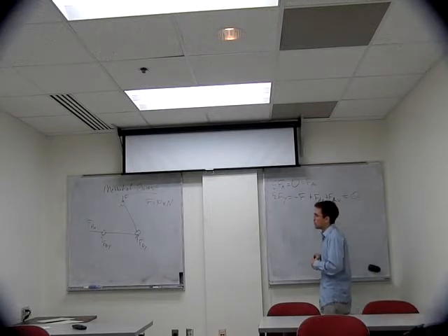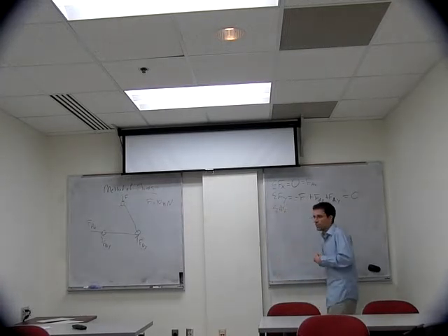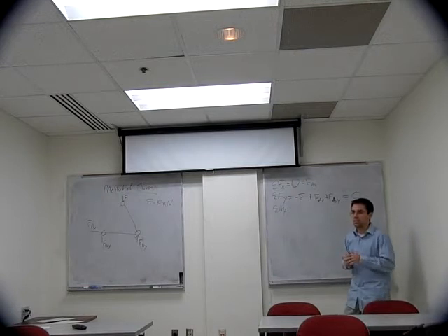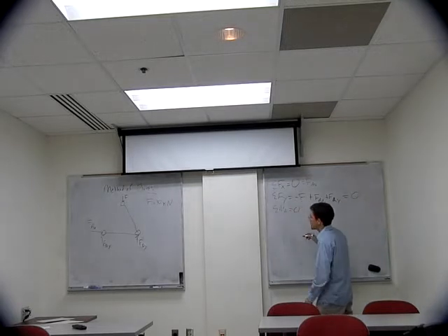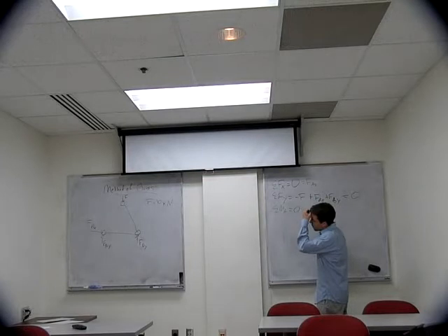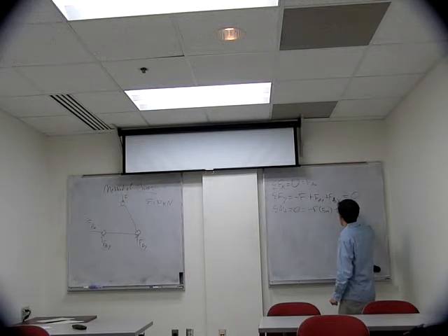So what we can do is take a moment around joint A. We know that since this is just a pin joint, there can be no torques around this joint. So this moment has to be equal to 0. So if we look at the moment, we have our applied force, which is 5 meters away, and we have our reaction force at B in y, which is 10 meters away.